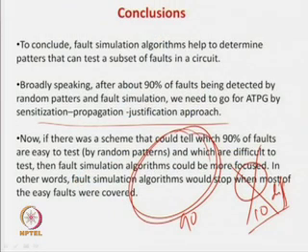But here, if nobody tells you which is the easy fault and which is the difficult fault, then you are in a blind case. Even for these 10% difficult to test faults, you are applying the random test pattern generation based algorithm and you are failing every time. For all the random patterns you are not able to generate a test pattern for this.